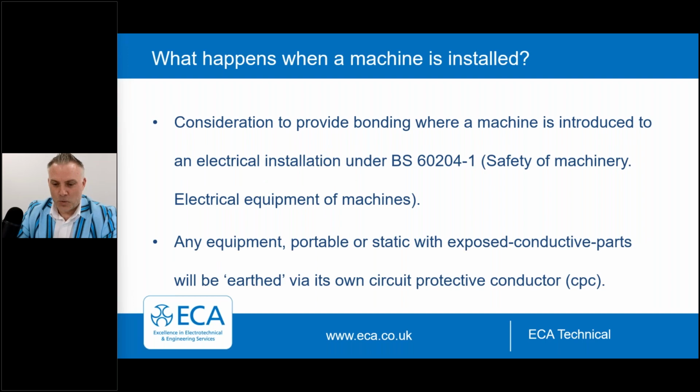Now, we don't just stop there. So we're not saying no, and we're not saying yes. What we are saying is considerations are required when you perhaps put a machine in. So we introduce a machine, and that's under its own British standard. It may require bonding. So any equipment, portable or static, with exposed conductive parts should be earthed by its own circuit protective conductor, the CPC.